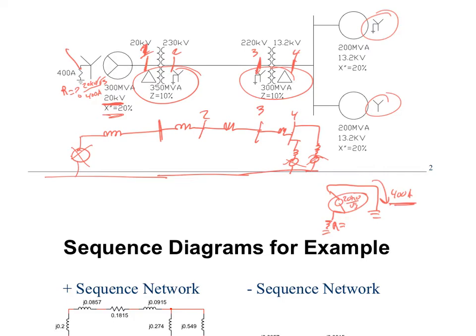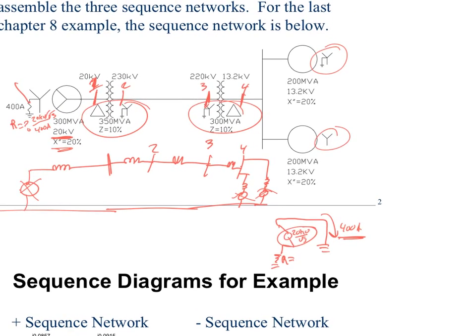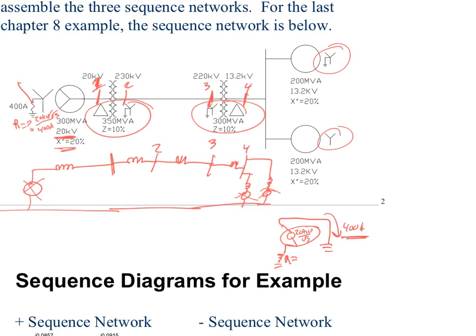So let's make myself a little more room here. So now I have my zero sequence, I have my reference bus. This is 3 times that neutral impedance. I have my generator. Then I connect to bus 1. How do I get through that transformer? Dead end on that side. It's dead-ended on this side. Up and through. Bus 2, right? Because of the delta-Y transformer.